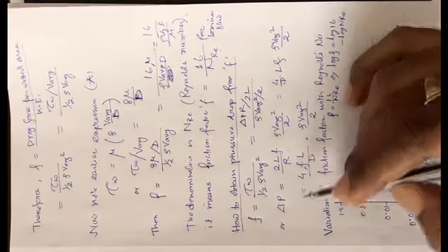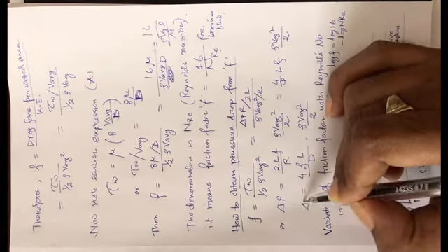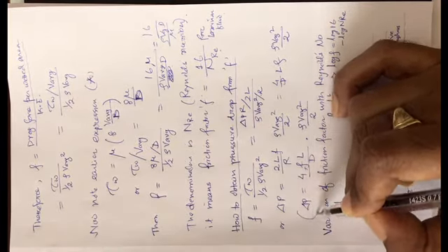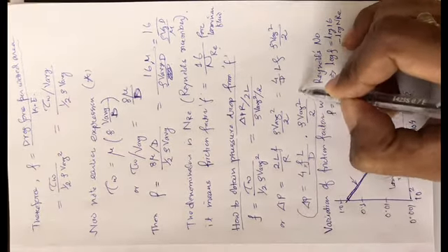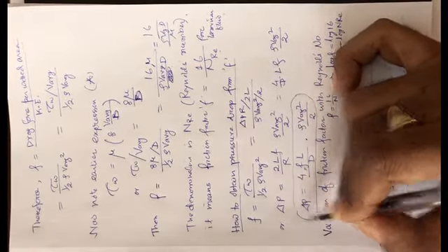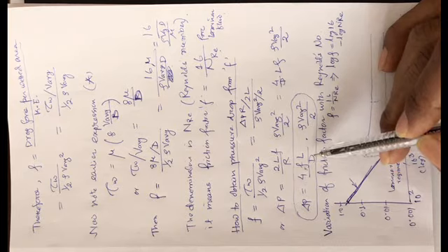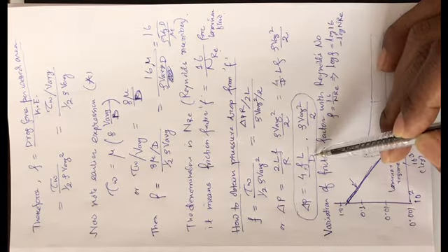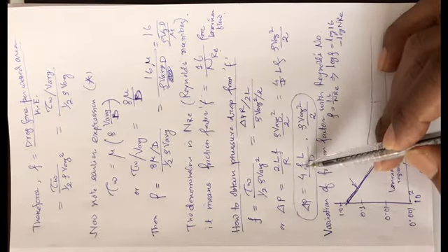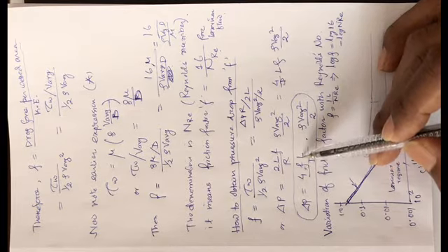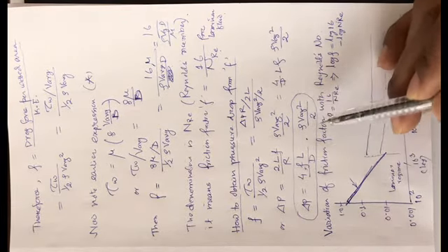So this is quite important. The friction pressure drop inside a tube or any conduit, you can always estimate by using this principle. In the case of a circular conduit, this D will be the actual diameter of the tube, F is the Fanning's friction factor, L is the length of flow, and this is the kinetic energy here.